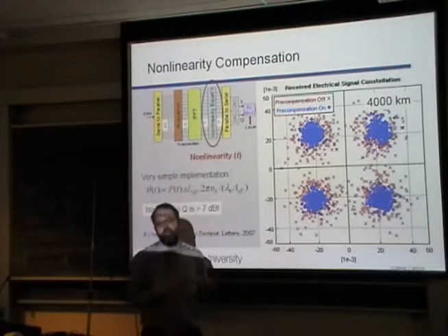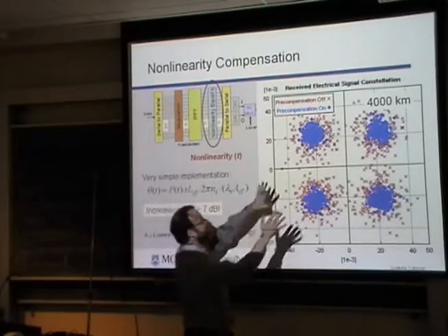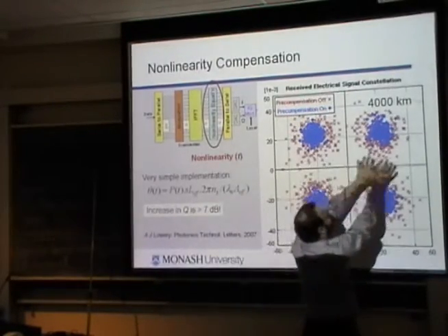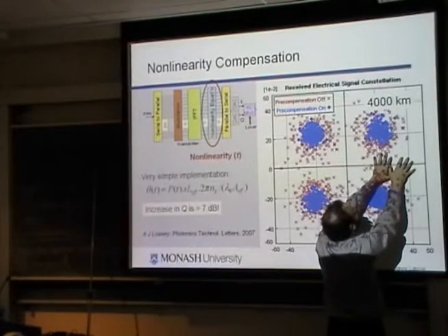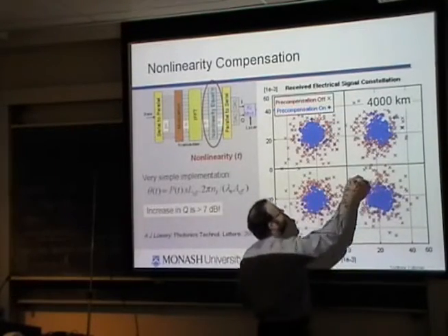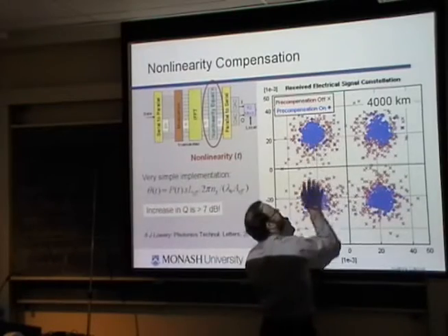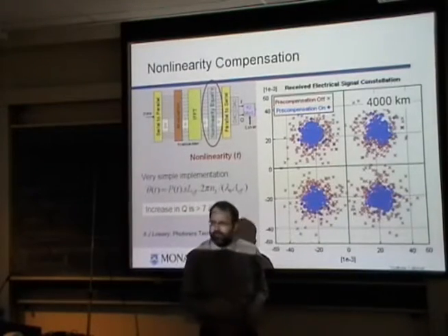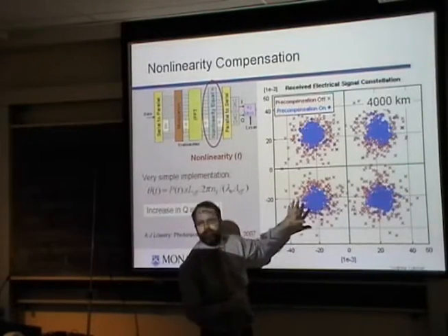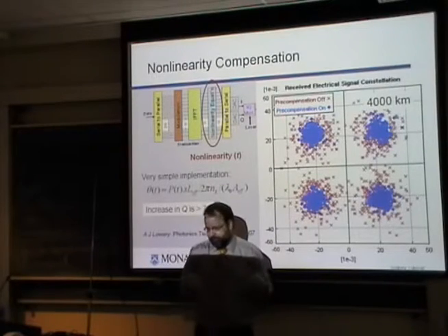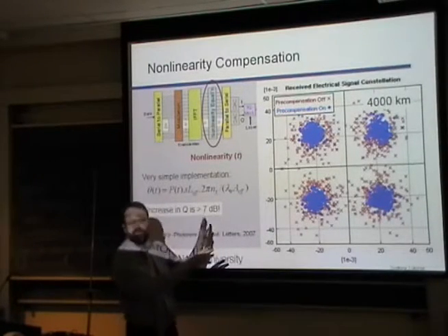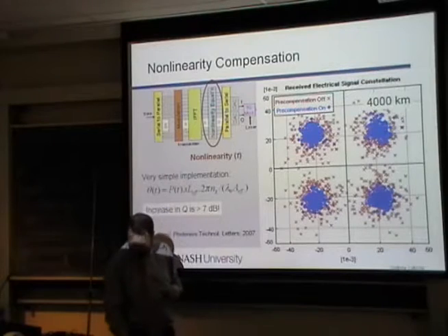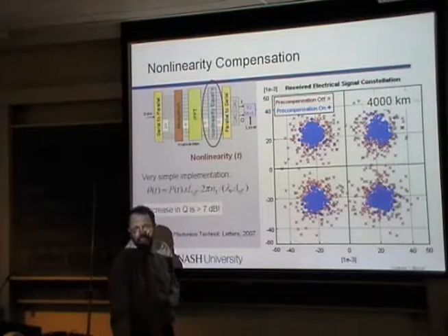And you can send 2 bits instead of 1 bit. So instead of having a splodge here, a 0, and a splodge here, a 1, you can have splodges at different phase angles. And if you have 4 splodges, you define them with 2 bits of data. So you double the data rate using that modulation format. Is that clear enough?